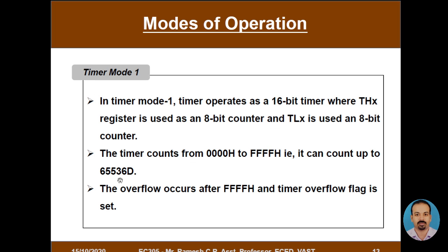So here the maximum count is from 0 to 65,535. So the maximum delay that is possible in mode 1 is 65,536 units.